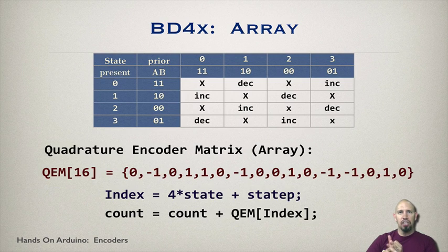Sometimes the compilers will not allocate memory for those variables because they say, oh, we don't ever use those variables, so we're not going to allocate space for them. That's why you have to use the volatile declaration, because otherwise the optimizer tries to optimize time and space on the microprocessor, and it'll optimize some of those things away, and you don't want it to do that.